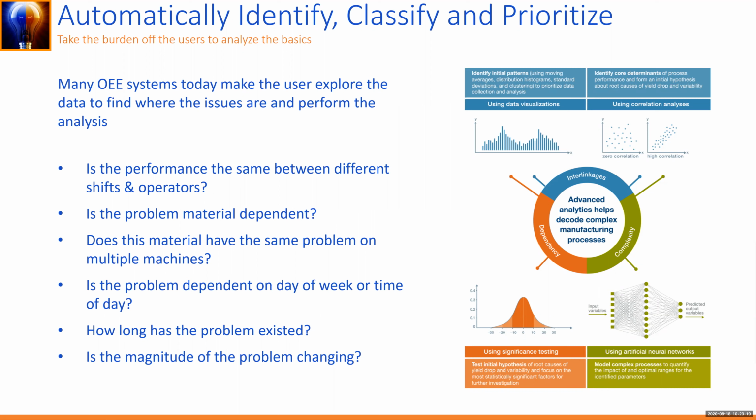Again, there are areas where it could improve, but the thing that those systems typically don't have is any context coming in from the people in the system. So they don't understand anything beyond e-stop. If you have a machine that gets an e-stop, they don't understand what really drove that. And so they're limited in terms of what types of downtime you can address using those systems. If it's something that the PLC knows about, they're great. If it's something that the PLC doesn't know about, then not so much.